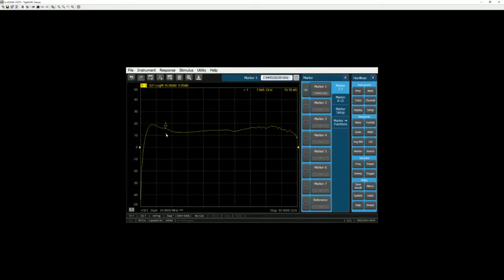Today we're going to just focus on the 4.75 gig range. So it reaches somewhere about here. Currently the input power is -15, and according to the sticker on the preamp, it says do not exceed +10. Again, just for the sake of verification, let's test it using another option that's available in the PNA. We call it gain compression. This feature enables users to quickly find the P1 dB of the amplifier and then scale it down if you want it to work in the linear zone.